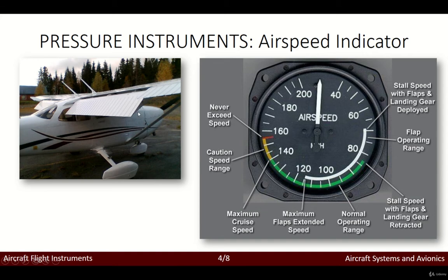Okay, basically what we have with flaps is that by using the flaps we can fly at lower velocities and also achieve high lifts. So the idea is, if we're operating at low speeds, both in taking off and landing, we will be using the flaps. This is why at lower velocity we only use flaps. We can't really fly without them, because the lift would be too low, okay, and the aircraft would essentially fall. Right, so this is, as I mentioned, the flap white arc.